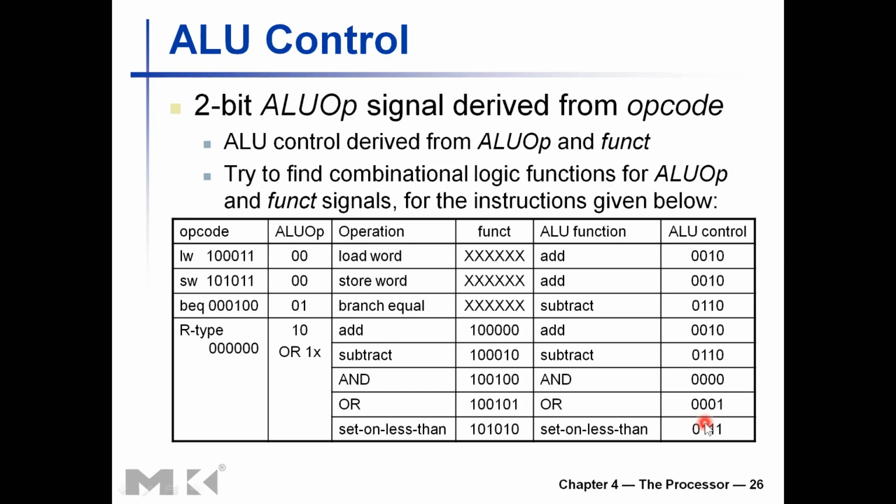Those decisions need to be done fast. So doing the ALU control in 2 stages makes the design of the control unit efficient. The signals that need to be generated faster are not hindered by other large logic circuitry which is needed a little bit later.